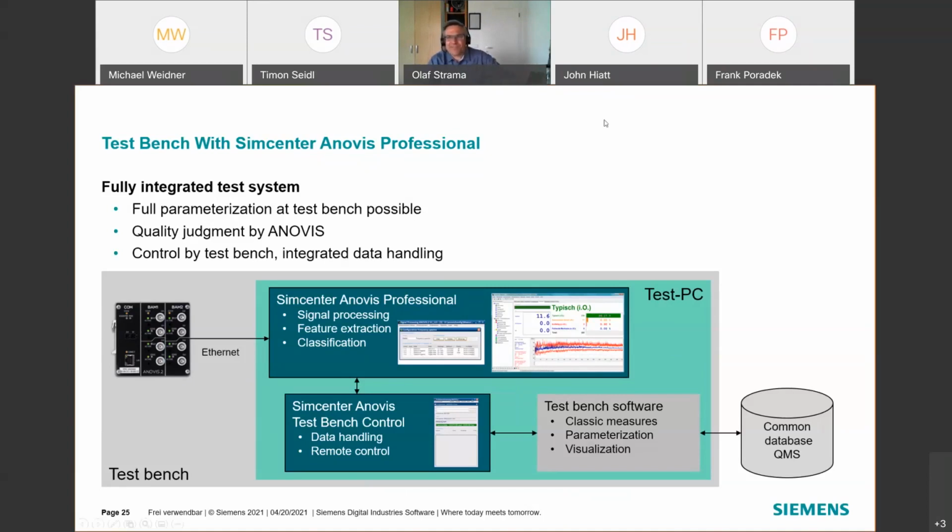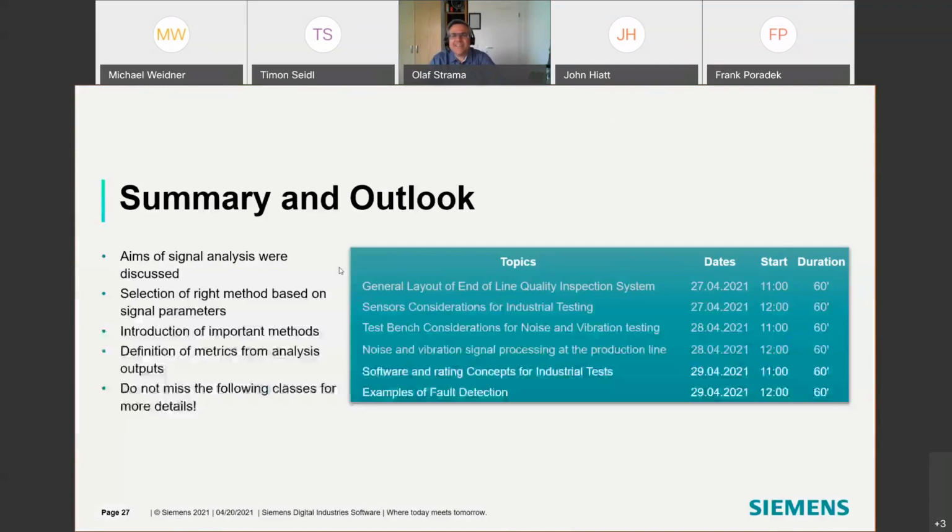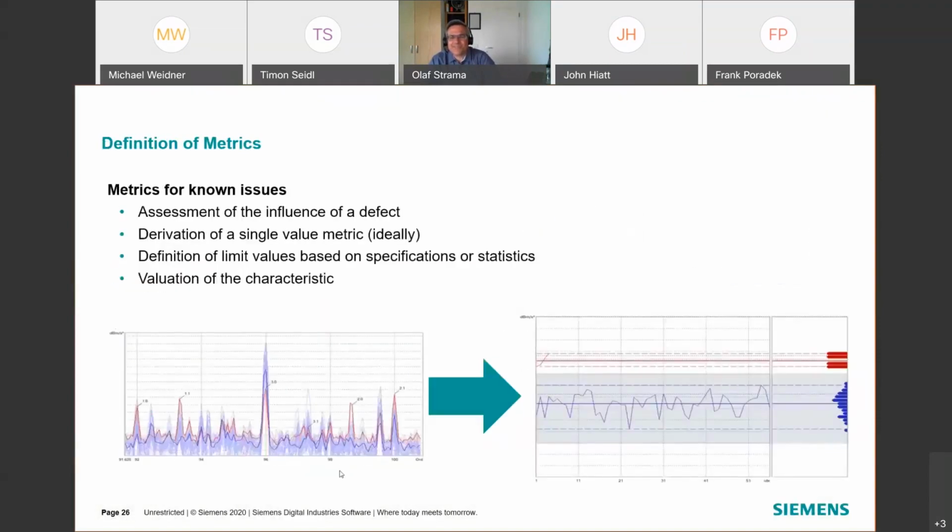If you remember this order spectrum, we know the components that we are interested in only contribute the gear mesh line and the sideband lines. Everything between those lines is external noise, and we do not care about this. So even if the noise changes between the orders, it has no impact on the orders themselves.